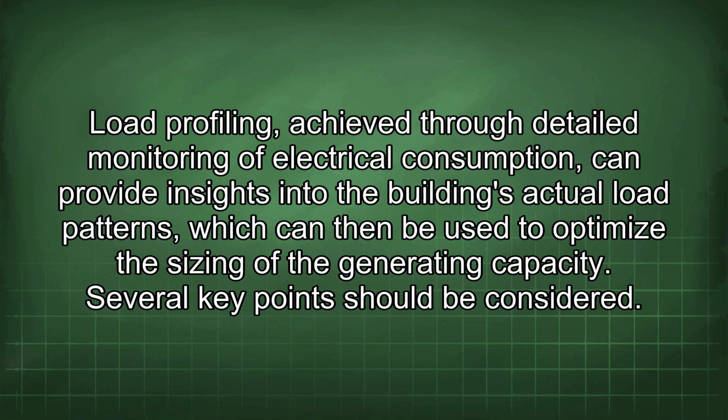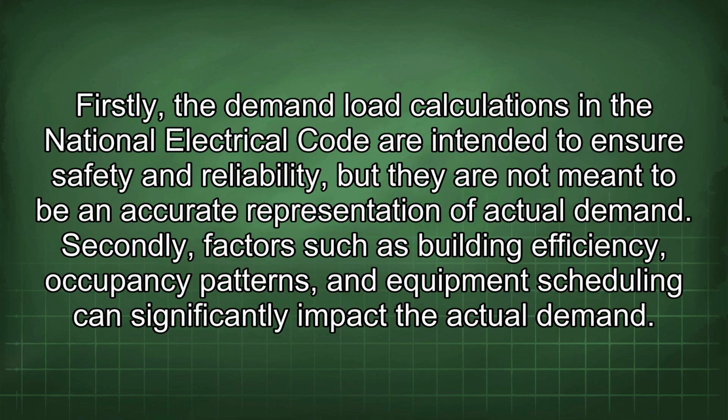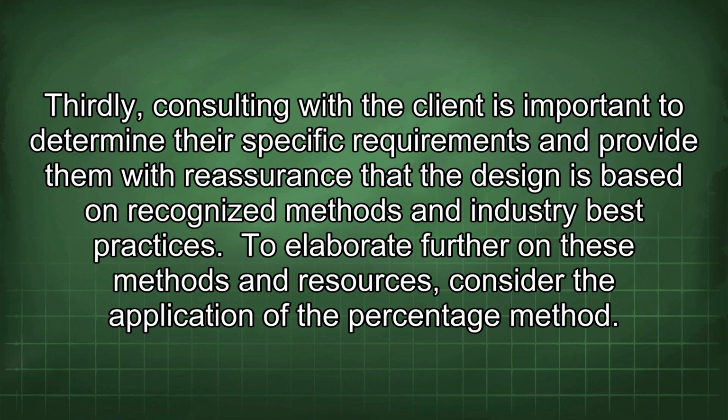Several key points should be considered. Firstly, the demand load calculations in the National Electrical Code are intended to ensure safety and reliability, but they are not meant to be an accurate representation of actual demand. Secondly, factors such as building efficiency, occupancy patterns, and equipment scheduling can significantly impact the actual demand. Thirdly, consulting with the client is important to determine their specific requirements and provide them with reassurance that the design is based on recognized methods and industry best practices.